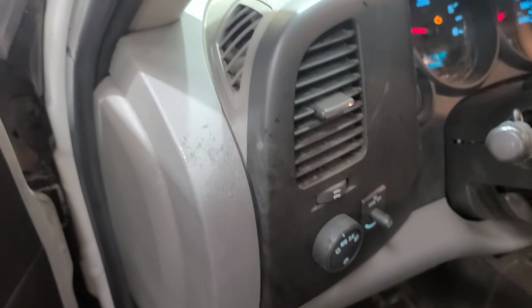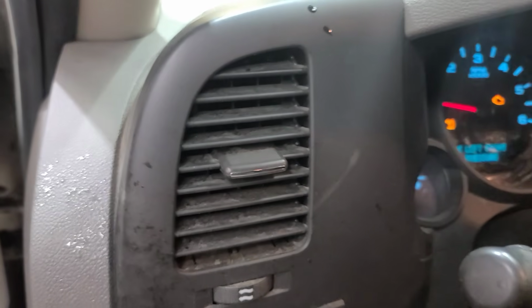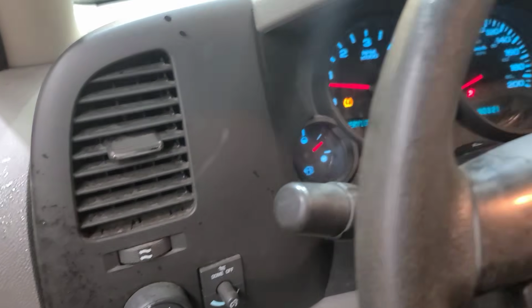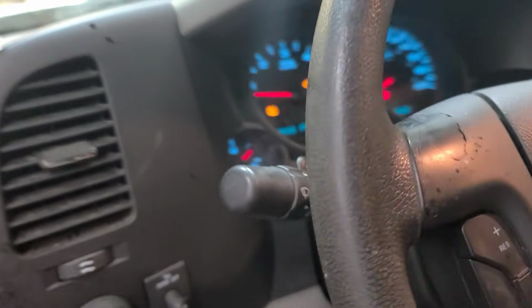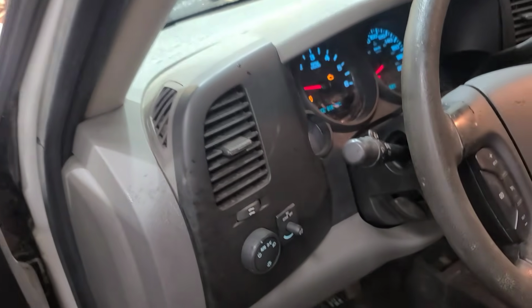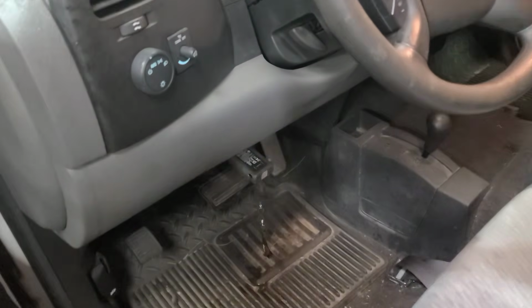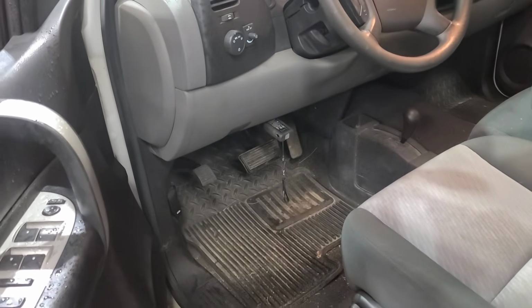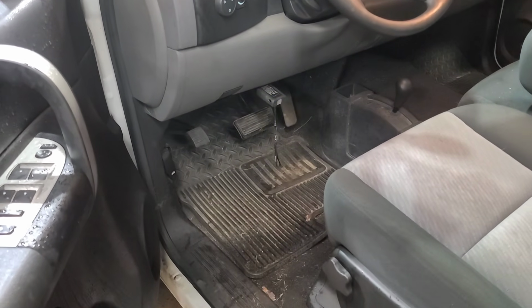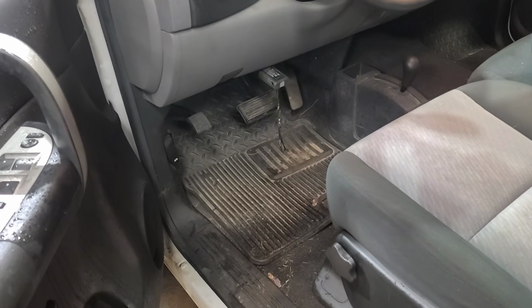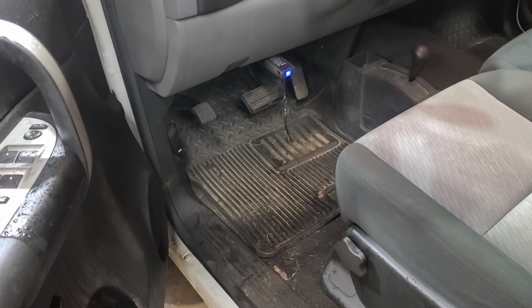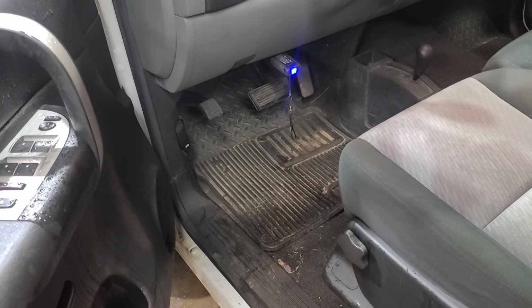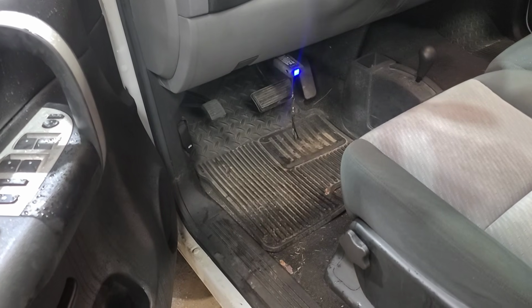And they apparently fixed some wires to the CAN bus on the fuel pump driver 6 months ago, but now this problem seems to have risen again, or is another issue. So we're going to go through a network scan on it and see what kind of codes it has to offer, maybe look at the network activity on 6 and 14, terminating resistance.